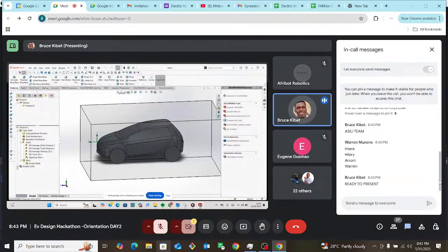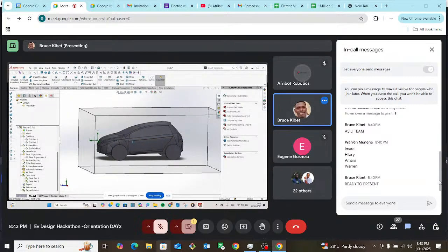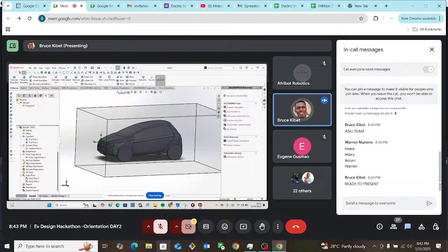So we did CFD on the shape. I designed the top part as a surface, so I had to turn it into a body so that I could perform CFD analysis. I think SolidWorks doesn't recognize surfaces. They are treated as zero thickness.